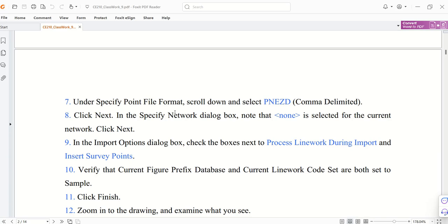A tree should appear as a tree. The benchmark should appear as a point, a triangle with a circle inside and a point, etc. If you have a fence, or for example the center line of a road or an edge of pavement, they should appear as lines. They should be linked together with a line. A surveyor does this job when he's surveying his points in order to facilitate the work later on.